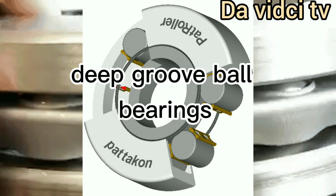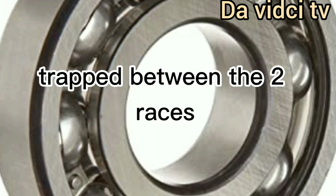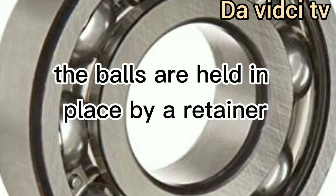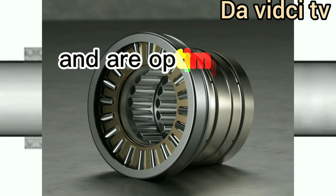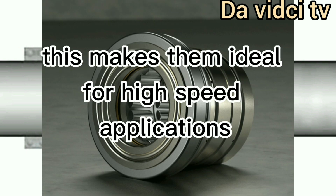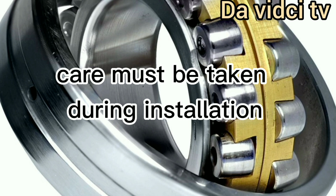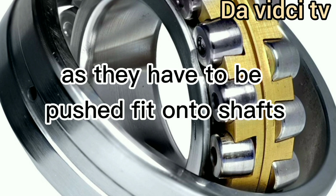Deep groove ball bearings. This is the most widely used ball bearing type. Trapped between the two races is a ring of balls that transmit the load and allow rotational motion between the two races. The balls are held in place by a retainer. They have very low rolling friction and are optimized for low noise and low vibration. This makes them ideal for high-speed applications. They are comparatively easy to install and require minimal maintenance. Care must be taken during installation to prevent denting of the races, as they have to be push-fit onto shafts.